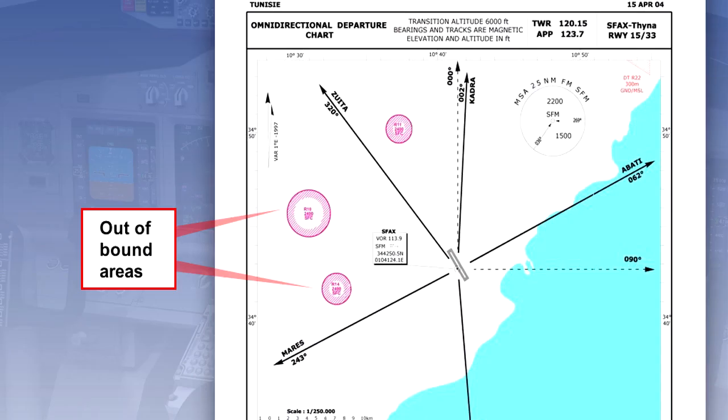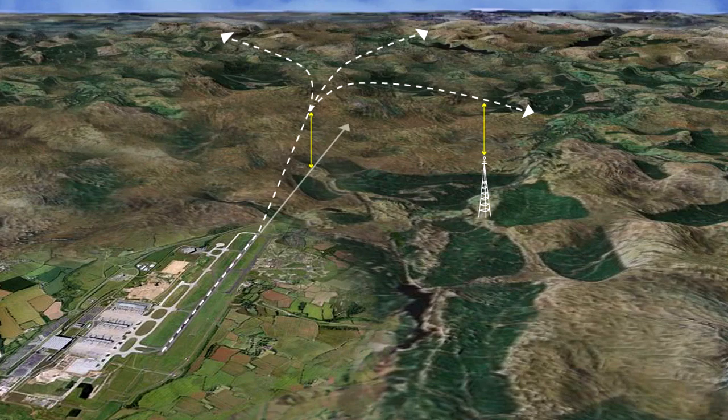It may be that some sectors of this departure area may contain an obstacle that precludes departure in that direction, but this fact will be identified on the departure plates. The basic procedure determines that the aircraft will climb on the extended centerline to 394 feet before any turn can be specified, and at least 295 feet of obstacle clearance will be provided before turns greater than 15 degrees will be specified. If obstacles don't permit omnidirectional departure procedures to be designed, straight or turning departure procedures must be produced. Alternatively, it must be ensured that ceiling and visibility will permit obstacles to be avoided by visual means.